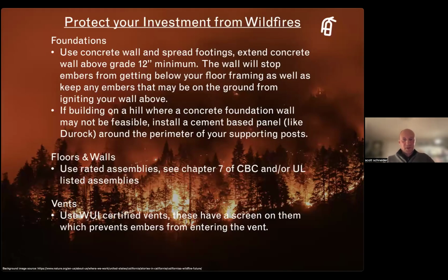And then I have a couple slides about protecting your investment, especially if you're in a WUI zone. And foundations, I mentioned this before, you can use a wall or a stem wall and extend the concrete up above the grade, and that'll stop embers from getting below your floor framing and igniting your framing.